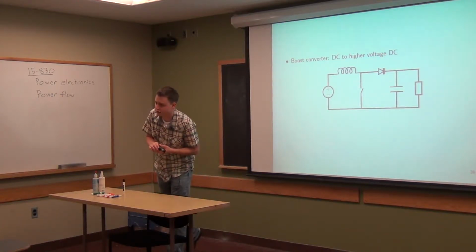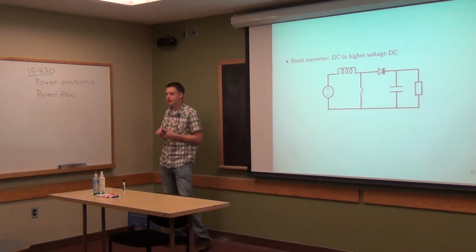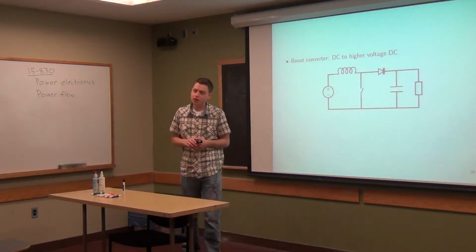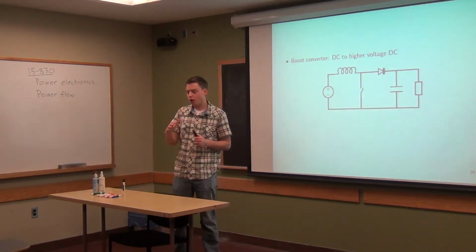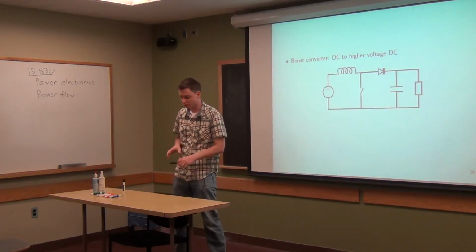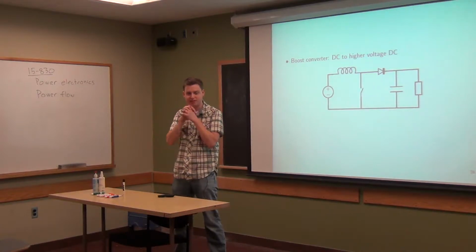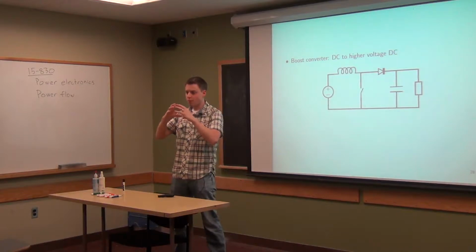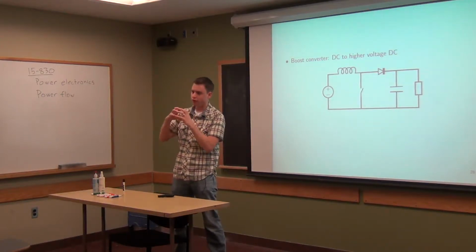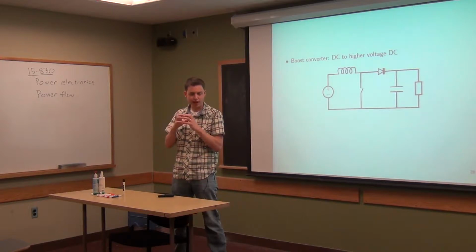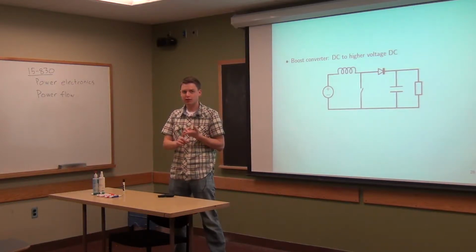Okay. There are, in some cases, so one case that actually is very important is underwater cables. Transmitting power underwater in an AC cable causes big issues with the size, and I forget exactly what happens here, but I think if you want a big enough cable to transmit a lot of power underwater, the size of the cable means you end up having a lot of parasitic effects.